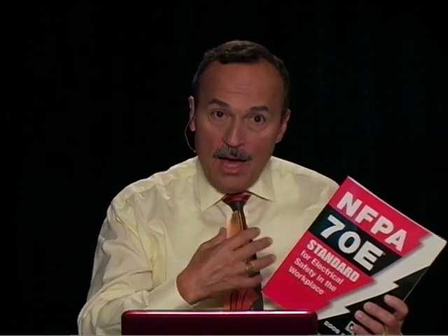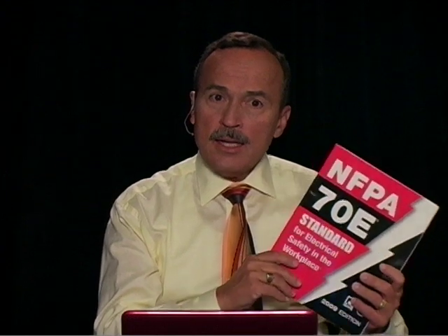All right, let's go back here. NFPA 70E gives us the information how to calculate the proper protective equipment to use and how to deal with the situation. But understand, the calculations based upon this is assuming that it's a bolted fault with the worst possible case, the lowest amount of impedance, and the protected device has a certain amount of trip time for that bolted condition, and therefore it does the calculation. This is the energy, the incident energy, and this is the clothing that you could use. Well, it's highly likely that the fault is not going to be a bolted fault.